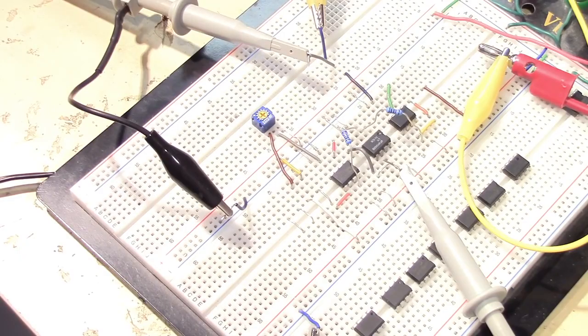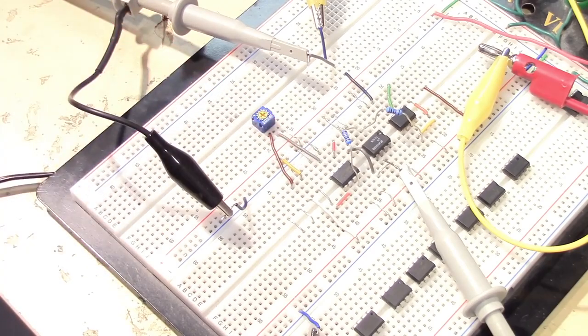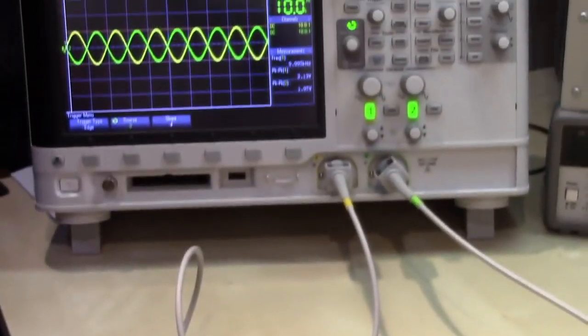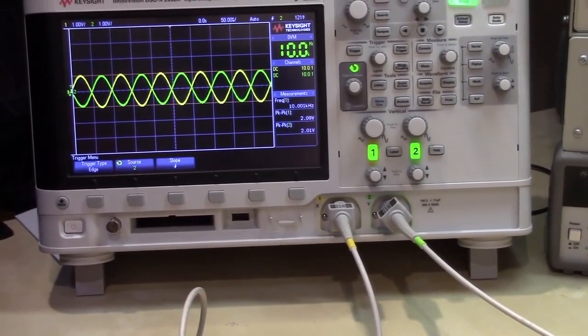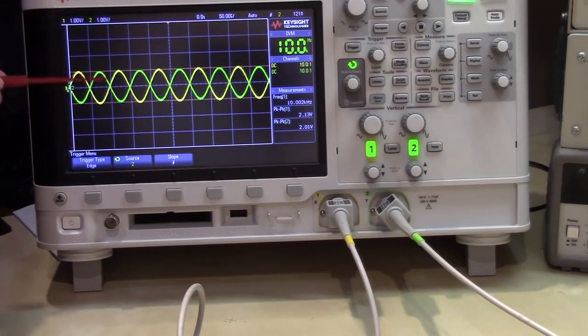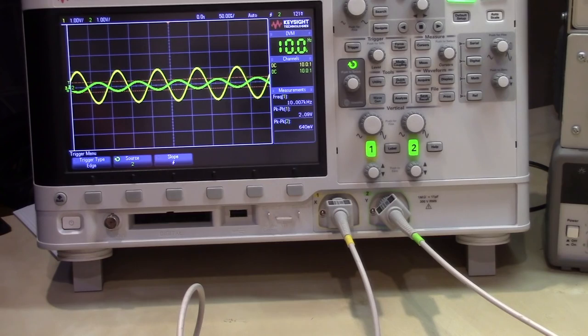And to demonstrate this, I have that same circuit built up on the breadboard here with just a little trim pot that allows me to set the control voltage supplied to the analog multiplier. So right now I have the control voltage set at 1 volt, and if we look over at the scope, you can see that my input, which is the yellow trace in channel 1, matches very nicely with the output in channel 2, which is the green trace. But as I increase that control voltage, you can see the output starts to decrease. And so we're attenuating more and more that input signal because that feedback resistor is effectively getting smaller and smaller.